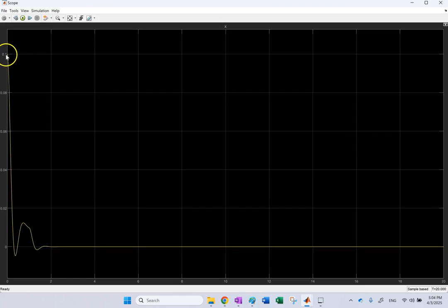There we go. You see, it starts from 0.1 with an initial slope of 0. It goes down. It has a little bit of oscillation. And then after about 2 seconds, all of those exponential negative 5t terms are now literally exponential negative 10, so they will all go to 0. So after about 2 seconds or so, all the energy of the system is damped by the damper.